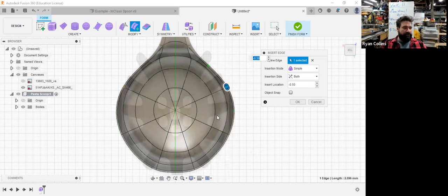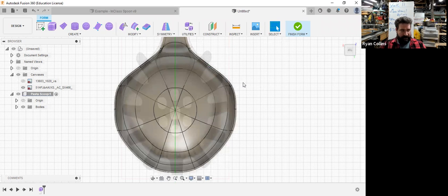So these tines are pretty evenly spaced, and that'll be just fine. So I'm just going to leave that, putting the location at right in the middle, which is 0.5. Negative 0.5 doesn't really matter in this case because it's on both sides. If I delete the negative, you see that it puts it right in the same spots. Great. So I'm going to go around and do that a few more times because I need how many? 1, 2, 3, 4, 5, 6. So at least 6 divisions. There we are. Select OK. It's going to keep reshaping things. Mildly problematic, but not a big deal.